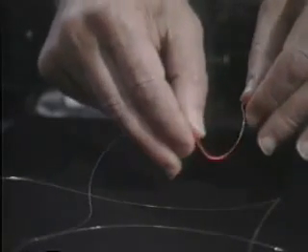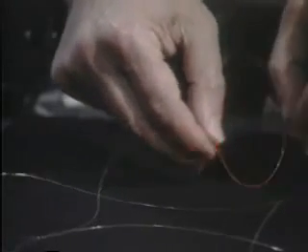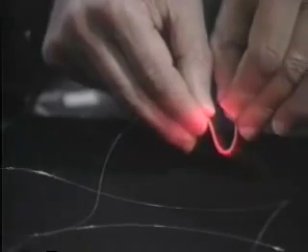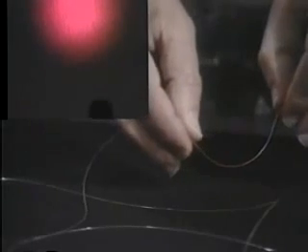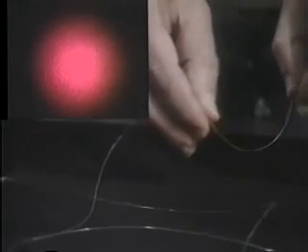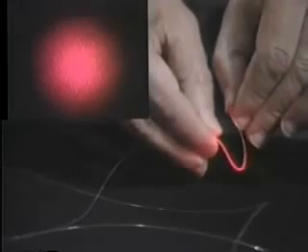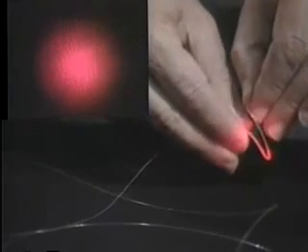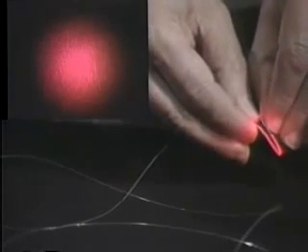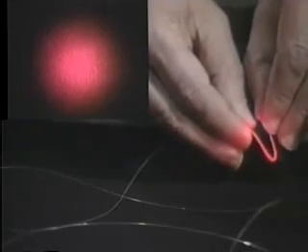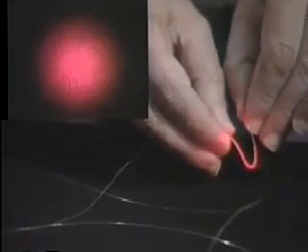All right, so here it is. It's very dramatic. As soon as you put a little bend in this fiber, you can kick out a lot of light. In fact, there's the glow right here. Now, if we can bring the output of the fiber into the inset over here, you can see that as I increase the bend, I'll do it even more, the intensity drops quite a bit, which means I've kicked out almost all the light by simply putting a bend into the fiber.